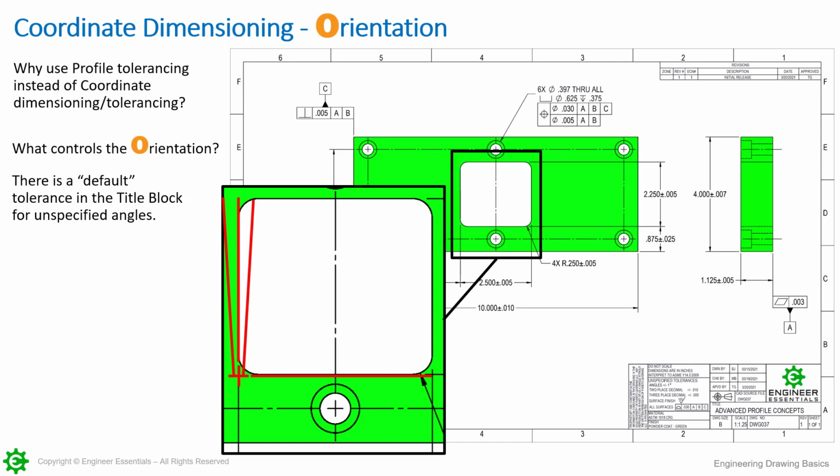But if you read in the standard, the radii, each one of them, do not have center marks with dimensions going to them. This means that what we call it in the engineering world or the CAD world is that these are corner treatments, and they aren't, if you will, the primary features. The primary features are the four walls, and that's why the dimensions are going to the intersections. The dimensions are not going to the fillets.